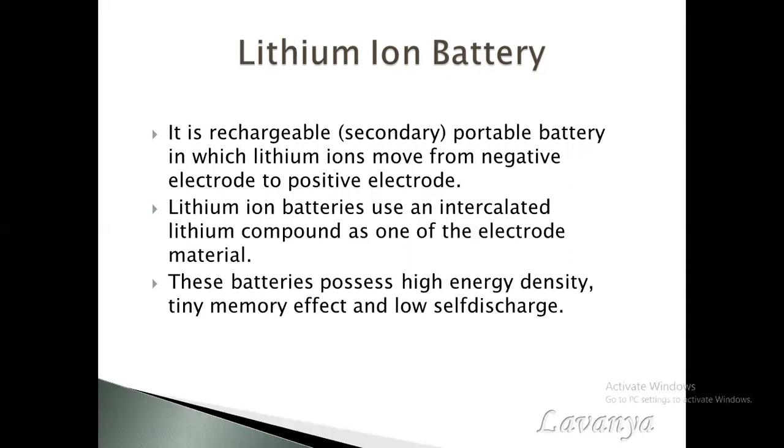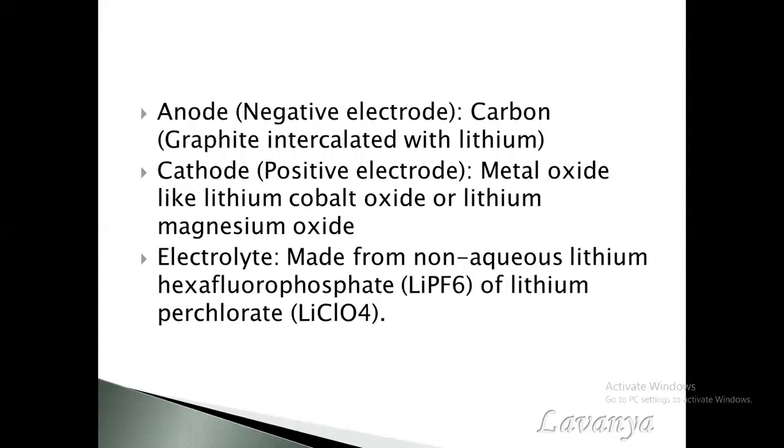Lithium ions move from one electrode to the other, positive to negative and negative to positive, in this type of battery. Lithium ion batteries use an intercalated lithium compound as one of the electrode materials, and they possess a high energy density and low self-discharging capacity.